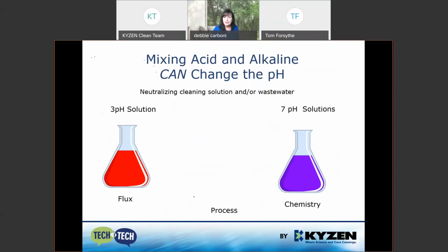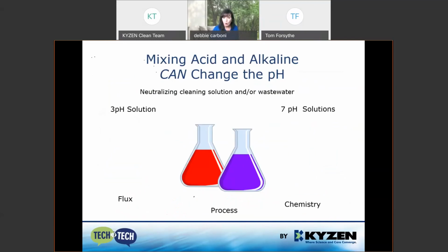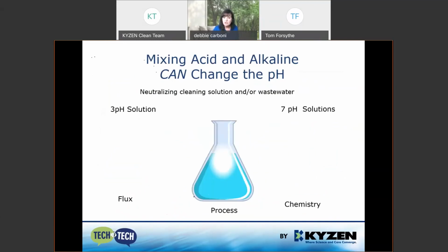Like we discussed earlier, all chemistries are designed for the task at hand. In our industry, that is mostly talking about cleaning flux. Most fluxes have a pH of somewhere between 2 and 3. If a product is engineered correctly, it will absorb these low pH soils without becoming low pH itself. You would not want to use an acidic cleaner on your assemblies. Your cleaning product needs to continue to clean and not harm your PCBs.